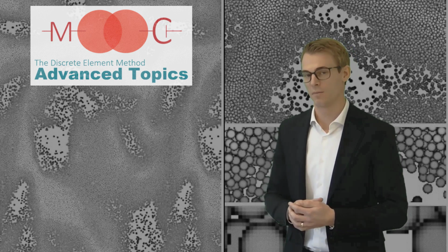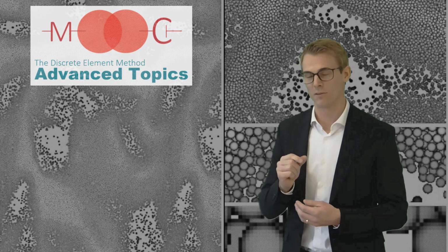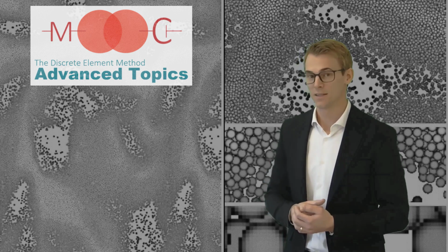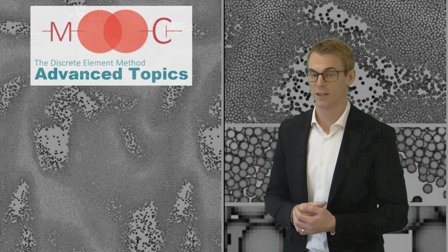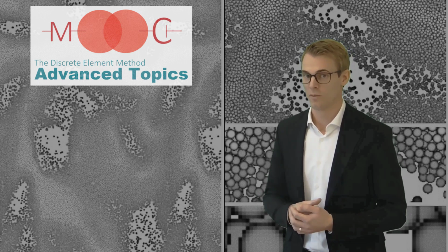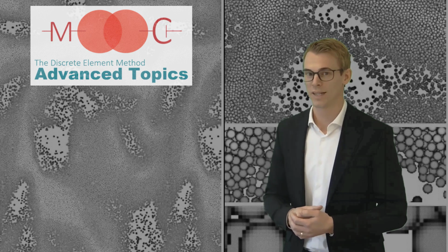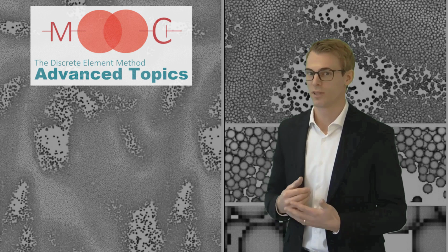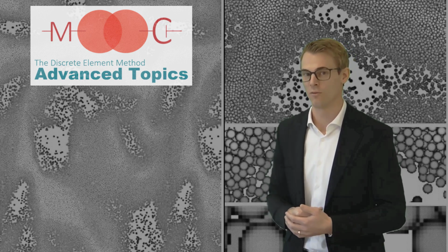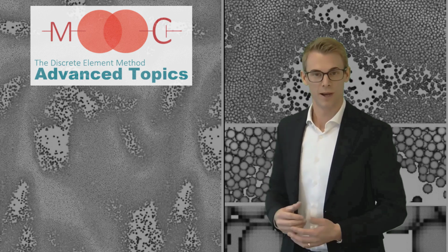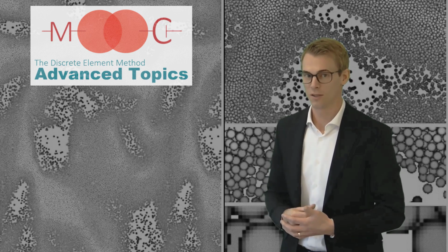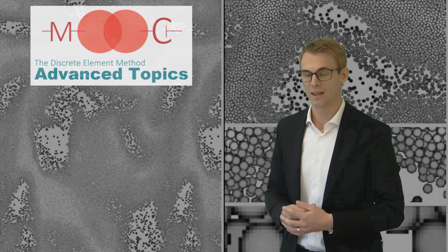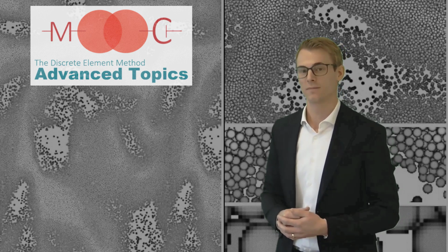On the other hand, if the particles are very small, the resolution is very fine, this leads to a lot of small particles and also to a lot of bonds. So with the computationally already expensive small particles, this results in a much more computationally expensive simulation overall. So it is required to balance computational costs with the need for fine detail in deformation or breakage.